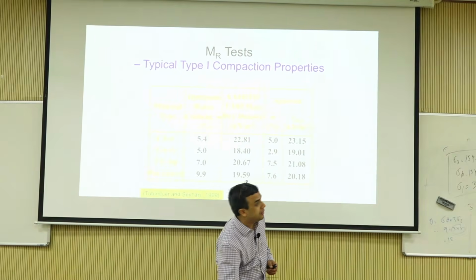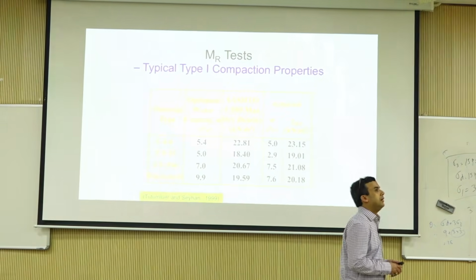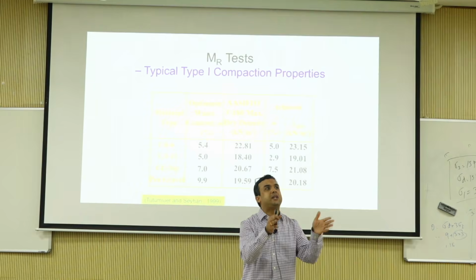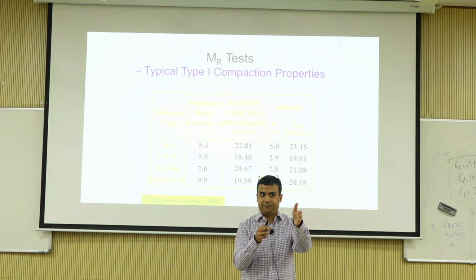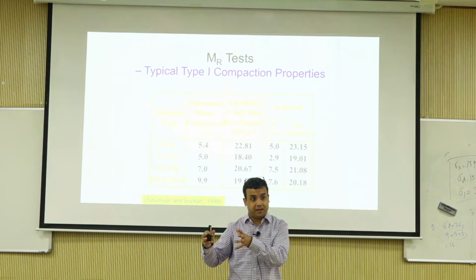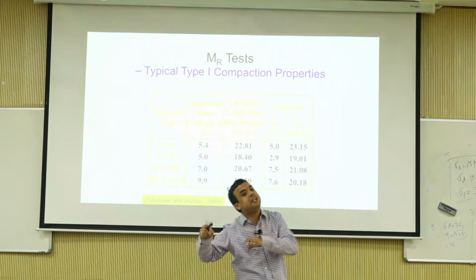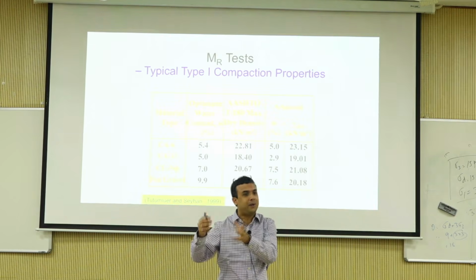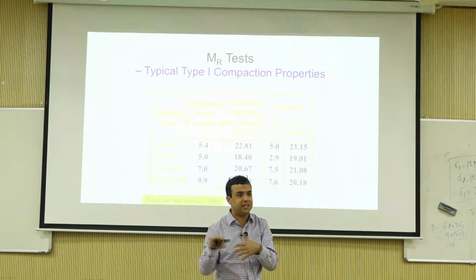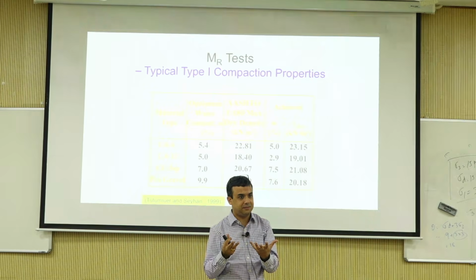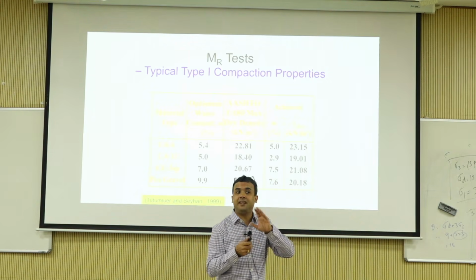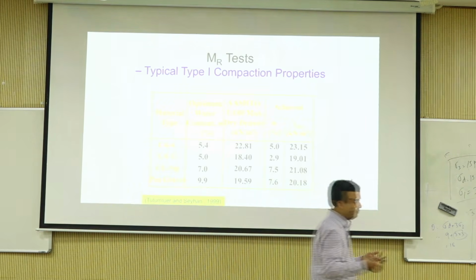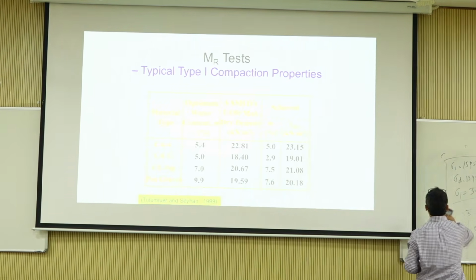Good question. Will the resilient modulus change between the 2 test procedures? Probably yes, right? Because now it is much more shaken. But what is more representative of what is happening in the real field? Their argument is that the higher-torture one is actually more representative, because you are shaking it under bigger stresses. So that's the reason I said it's not a specification test. It's a research test. So maybe the numbers are different. I don't have the comparison.